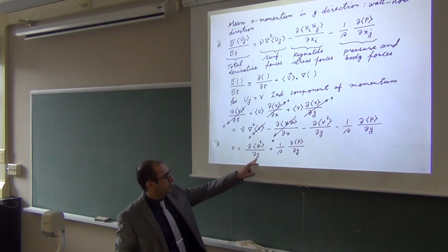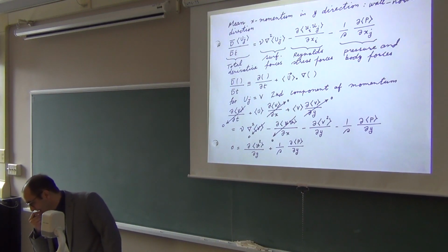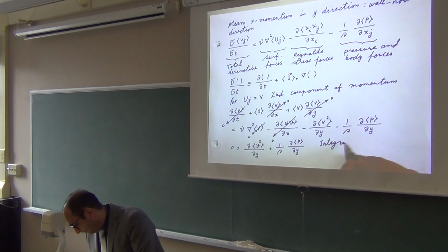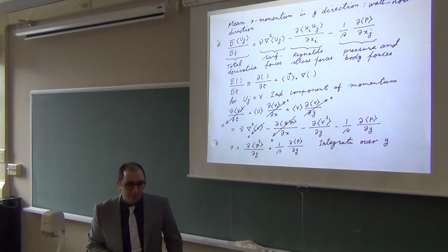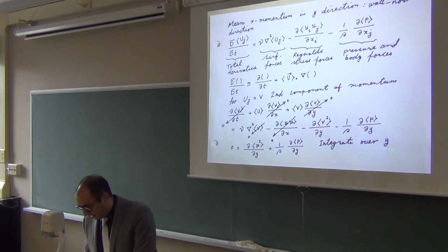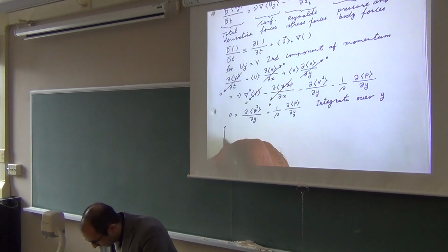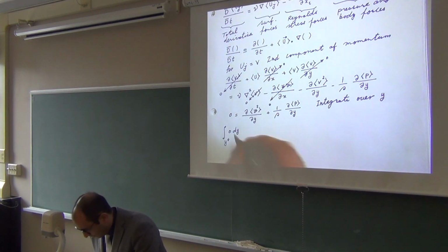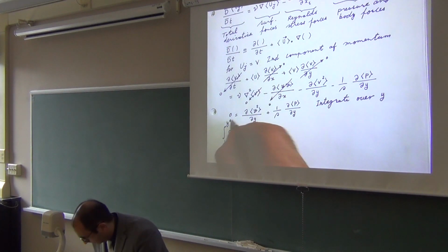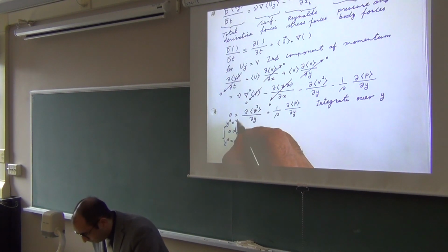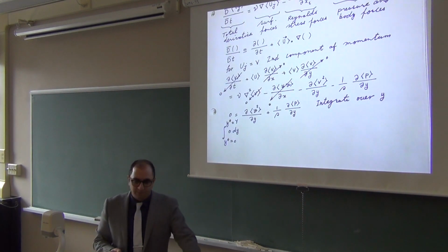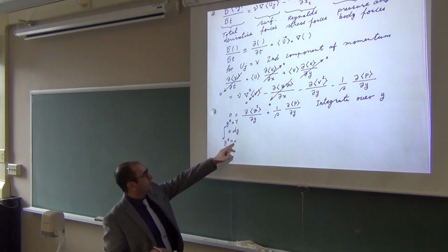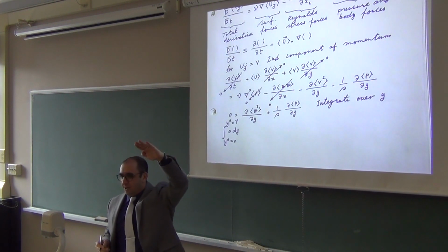Sounds like this is just a differential equation in the y direction. It's a very ordinary differential equation. So I can integrate this over y. I just integrate this in the y direction. I integrate the left-hand side, 0 dy, and I vary y from some initial value 0. I start from the bottom of the boundary layer at the surface. The y, or distance to the surface, would be 0. I integrate from 0 to some given height. I'm not saying I'm going all the way to the top of the boundary layer, but anywhere in between.